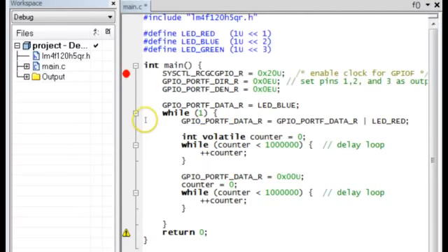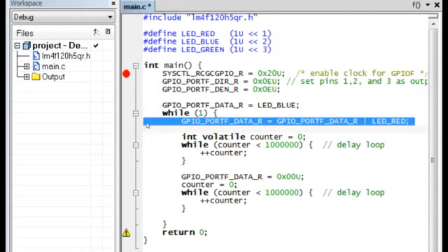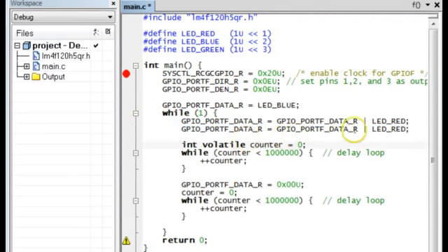Please note that this trick works only if you can actually read from and write to the GPIO-F register, so you need to check in the datasheet that this register has read-write permissions. The C language provides a special abbreviation notation for assignments in which the left-hand side also appears as the first argument on the right-hand side.